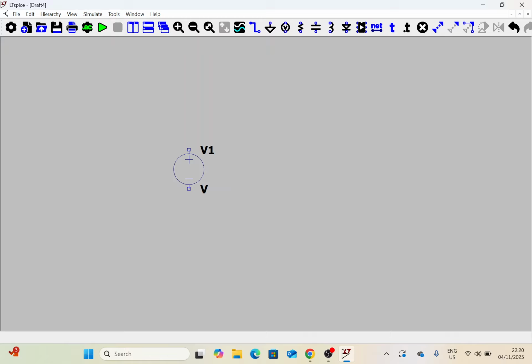For this video, because it's the first one, I just want us to do a very simple circuit simulation. So I'm going to pick a resistor here, and you can see that the resistor I picked is in the up down position, right? If you don't want it that way, you just press Ctrl R, and that's what's gonna rotate your component for you. I want it to be horizontal, so I'm just gonna place it here like that. And because I don't want to place any more resistors, I'm going to press escape on my keyboard.